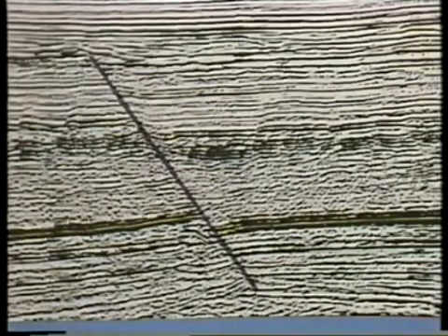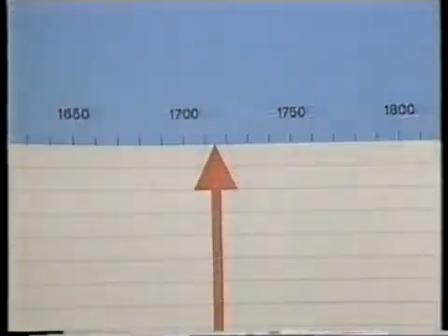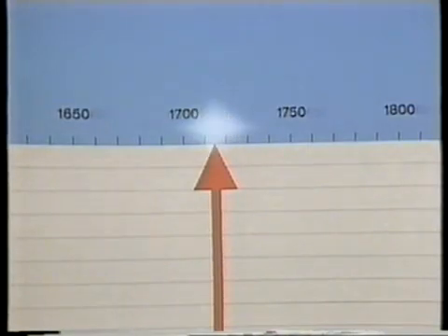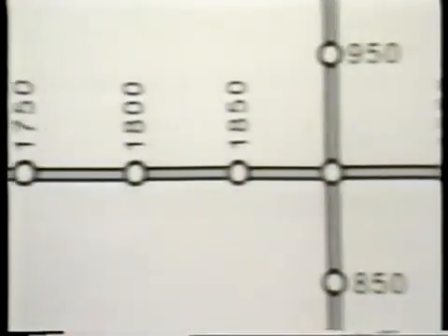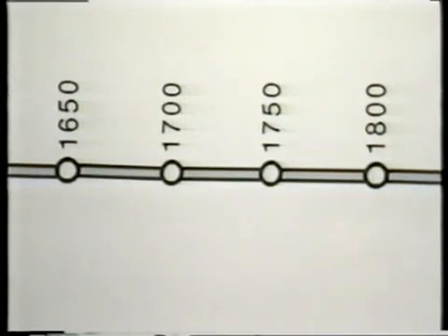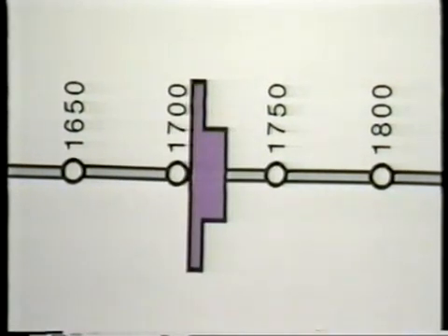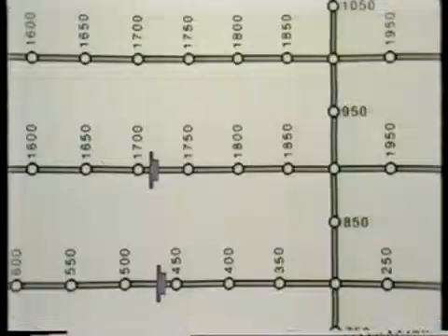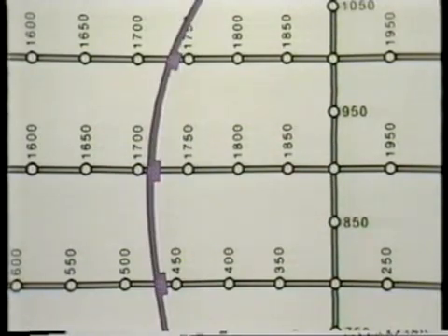Then, on line 4, again, the big fault, very clear, at shot point 1715. Again to the map, and mark the fault down to the east. And from line 5, the smaller fault down to the east. So the fault is, more or less, north-south, curved but generally perpendicular to the lines.